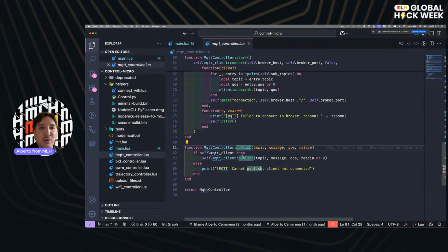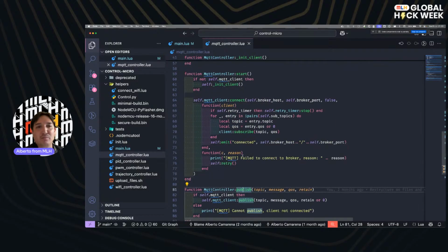So at this point, you already know what the MQTT protocol looks like and what you need to do. Create your client and start your subscriptions, and every time you want, publish your messages, and that's it, right? And manage how you handle your messages in the subscriptions, right? That's why it's very important to have consistency in your topics. You define your topics, so it's up to you.